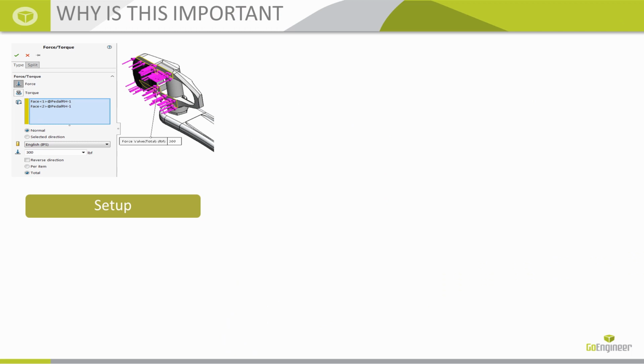First off, any simulation that you run, be it a CFD study or an FEA study, has 3 components. The first one is the setup, or pre-processing, where you're describing the boundary conditions, a fixture here, a load over there, what material is used, and meshing the model. All of that constitutes the setup.